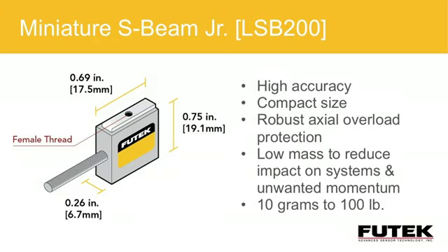The mechanical overload stop is also extremely important in automation applications where we have a potential for mechanical overload. This particular design is available in ranges starting down at 10 grams, where in these working ranges the overload stop becomes even more important. Just to explain the mechanism itself, if you look at the current slide, you'll see a female thread on the top of the load cell. We have a matching thread on the bottom, which you cannot see in this image. You attach to those female threads, applying a tension or compression load accordingly to provide stimulation to the load cell.